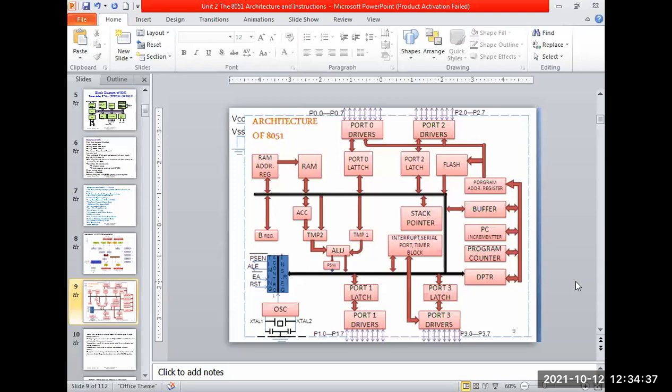First of all, this is the way of writing. RAB equal to, in one bracket 5 plus 3, because both are in series and that is the addition. That bracket is in parallel with 4, and that is in series with this 4.